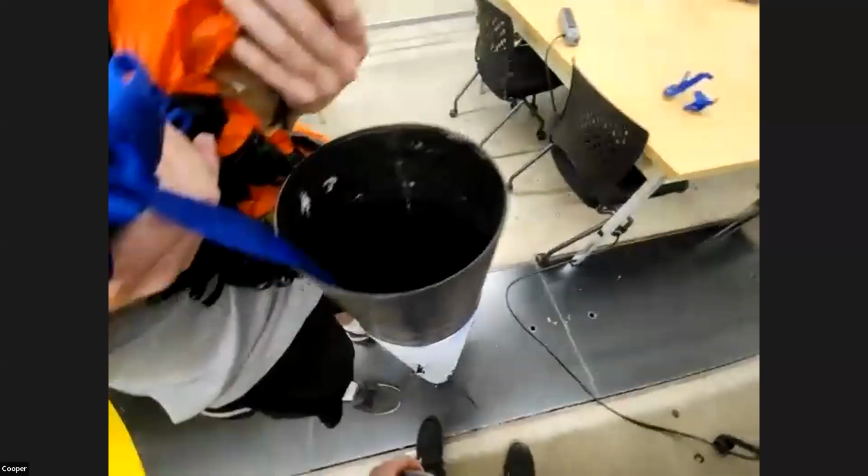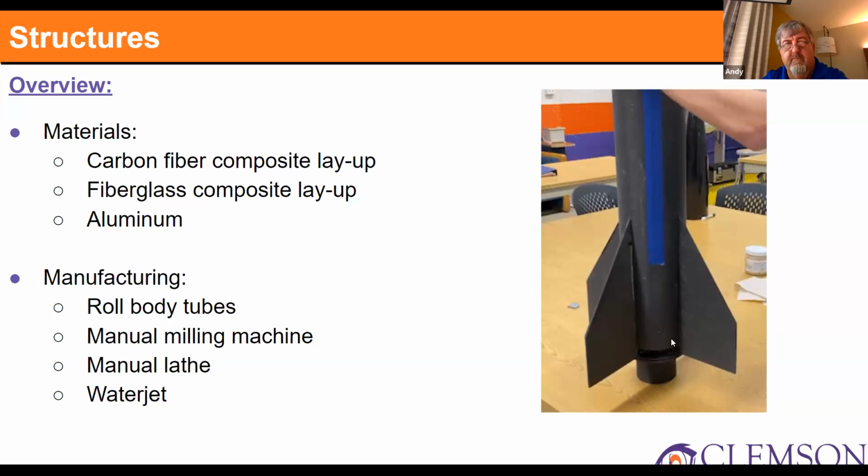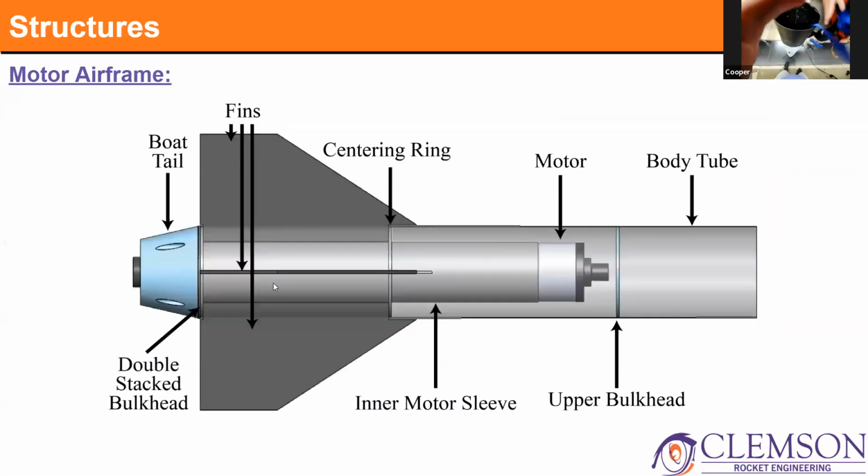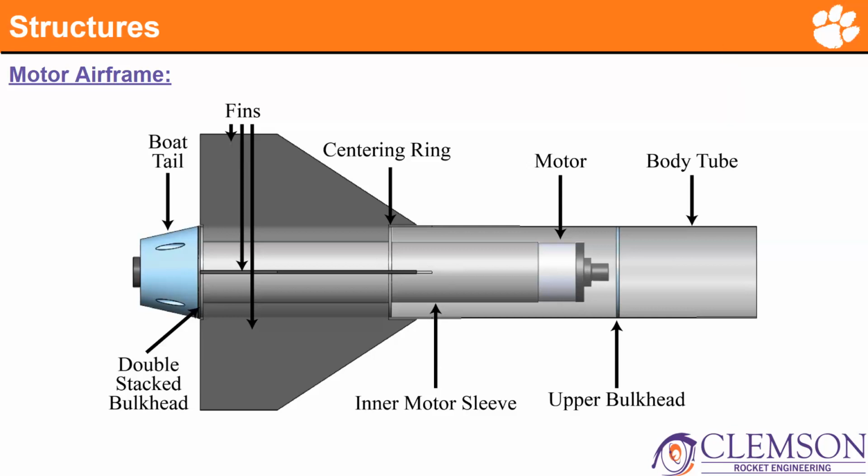Anything else? Well, so I guess at this point, since you're showing us the rocket, you guys start asking questions about it. So, okay, I'm seeing a boat tail. That's great. So I was about to say that that motor mount sticking that far out is a little wild. So the boat tail will be acting as your motor retention. Is that correct? Yes, that is correct.